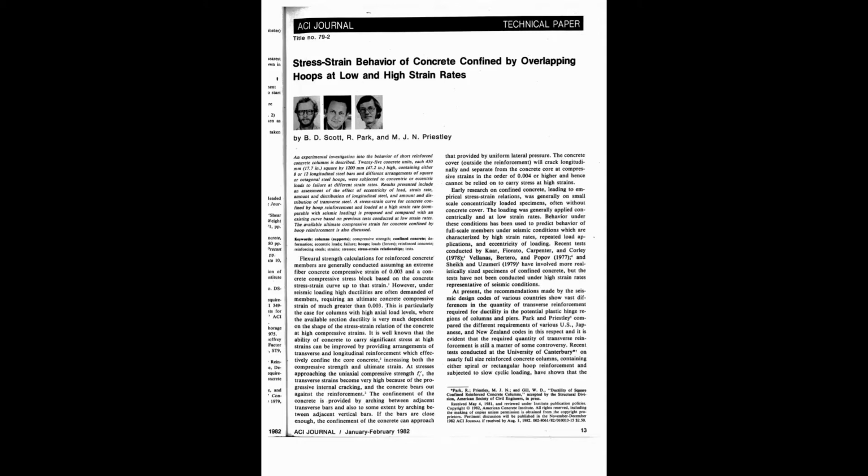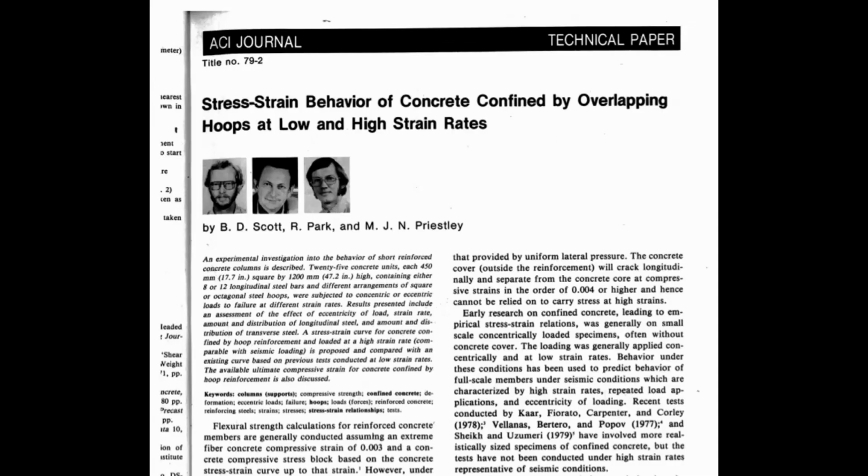So for the confined concrete in the core you will use one model, and for the unconfined concrete outside the core, we will use the other model. We'll be able to track the response of the structure through, and that will be very useful for you if you do concrete design.